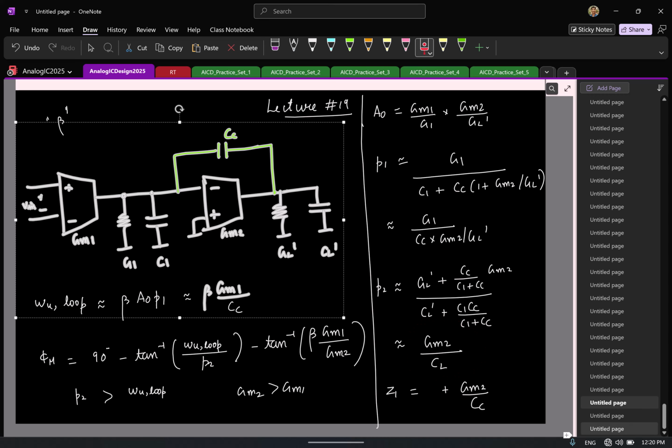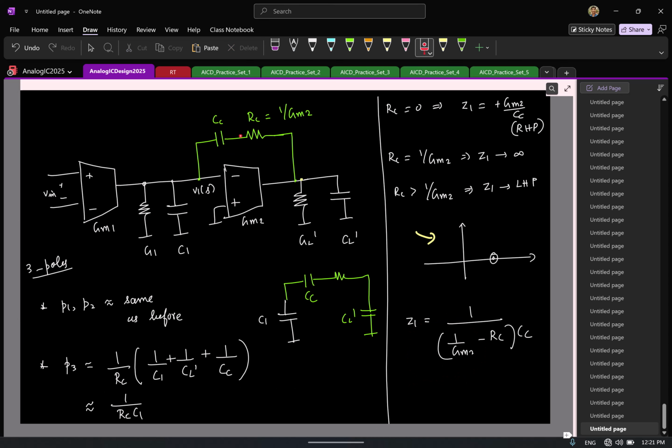Okay. See, remember that earlier when I didn't do this whole business, how many poles and zeros I had? 2 poles and 1 zero. So the 0 was in the right half of phase plane. So that was a bad thing. Now I wanted to eliminate that bad thing. I tried to do something. So of course the 0 has been pushed to infinity. But in that process, what did I do?